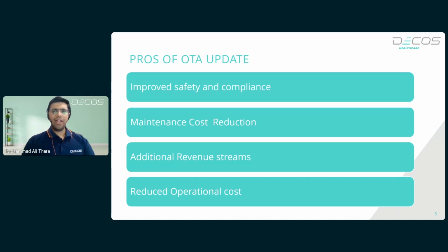While they are highly convenient for both IoT manufacturers and users, OTA firmware updates also have some drawbacks. For one, they require the device to be working and connected to the internet. In addition, the device needs to be shut down and restarted in order to complete the update, which can be a problem for scheduling the upgrade.